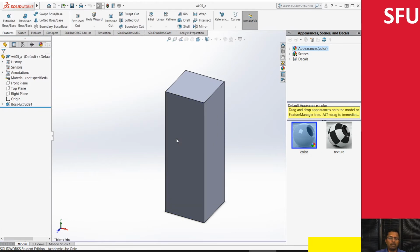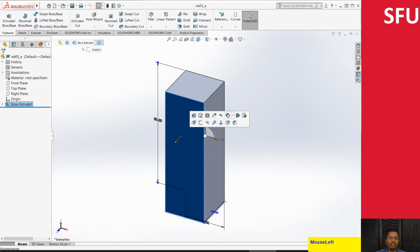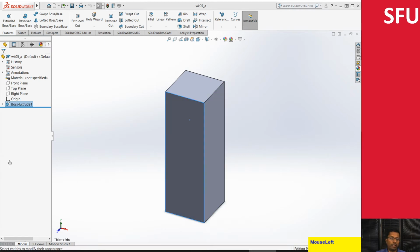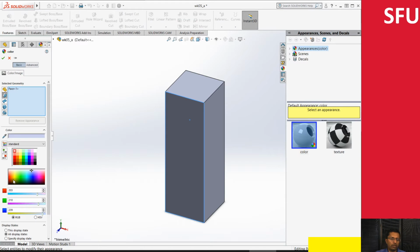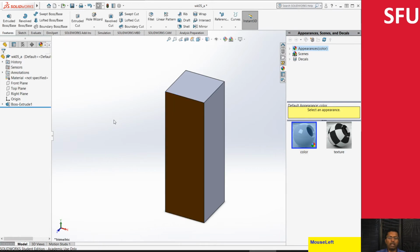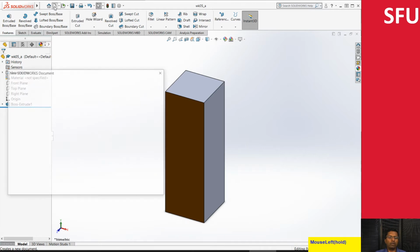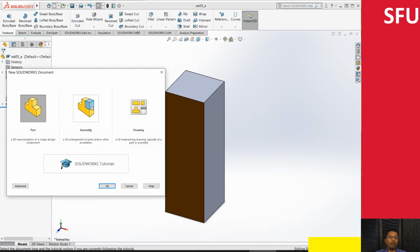And this is the other part that we previously created, and we're going to change the appearance over here. Then we'll change this to a different color. For instance, orange is going to be yellowish right here, and then we say okay. We'll save this part as well. Now we are going to create our new assembly, and it's not super difficult. What we do is Control N, and instead of clicking on part, we click on assembly over here, and then we say okay.